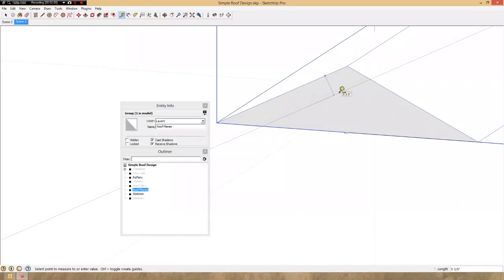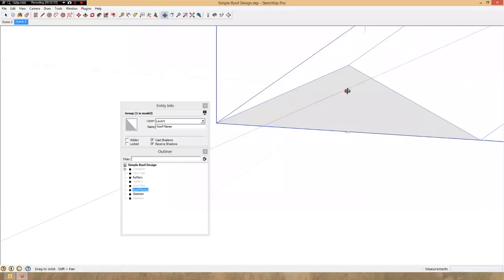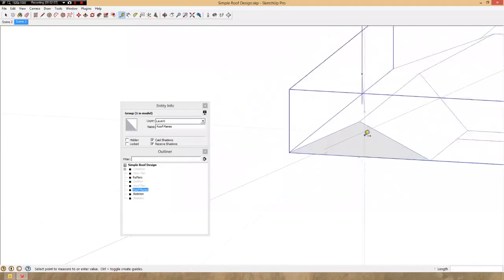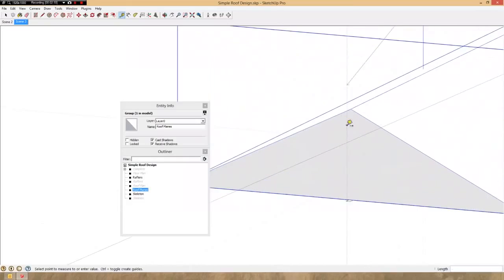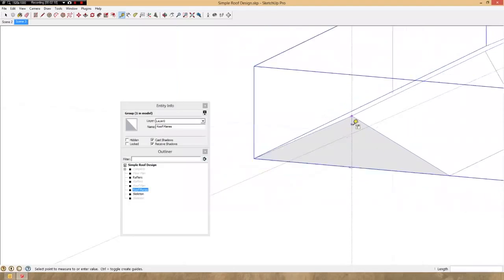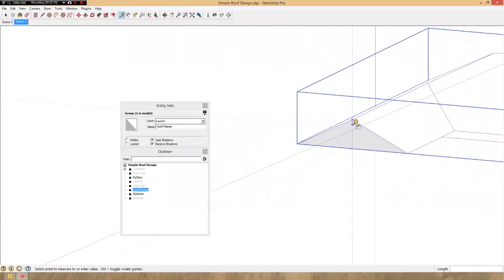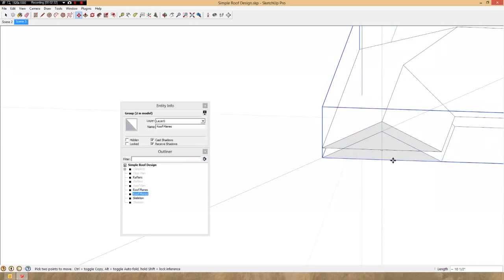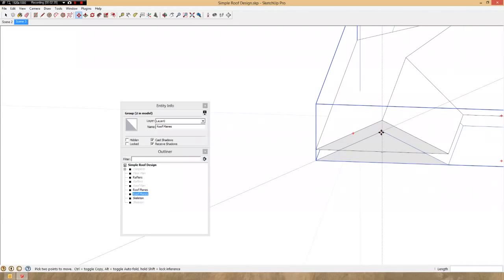Verify that we got it correct. Okay, 9 3/8 inches. Taking a plumb guideline, a vertical guideline off of the blue axes. And that's our plumb dimension of that, 10.5 inches. Let's select the roof planes, move tool, copy, and create a copy and drag it down that dimension.